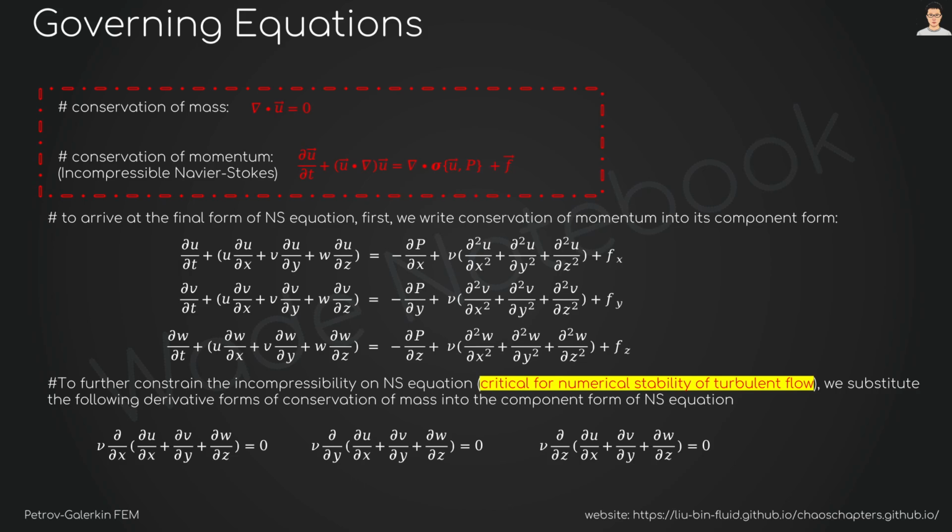However, what about the numerical stability of this partial differential equation system? Especially, if we increase the Reynolds number into the turbulent regime, the system becomes super stiff, which means the previously stable numerical solution becomes very sensitive to the numerical errors and/or background noise, and may quickly go into divergence in turbulent flow. To improve the numerical stability of the PDE system, it is advantageous to implicitly embed the incompressibility into the Navier-Stokes equation, besides the strong coupling with the continuity equation.